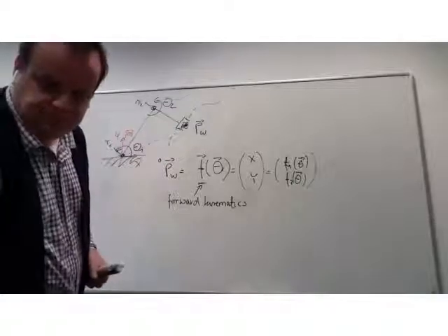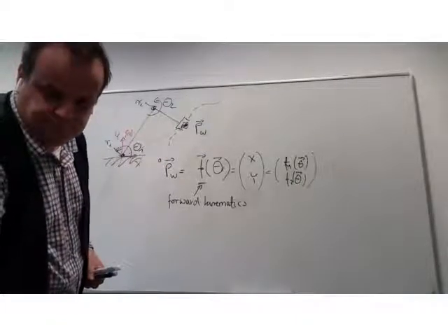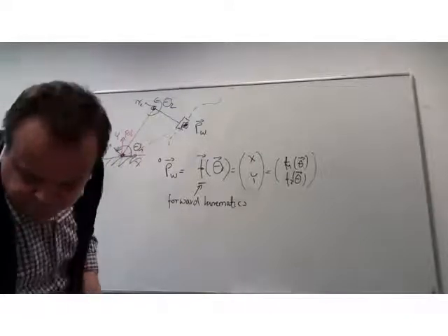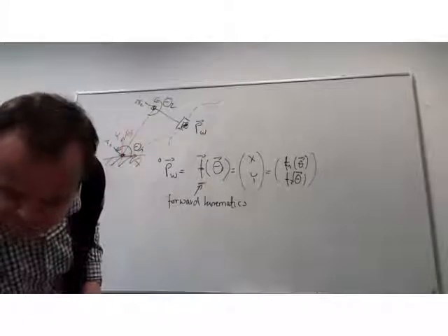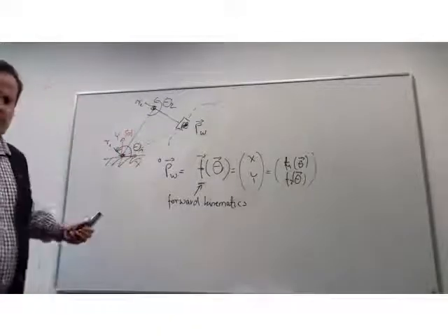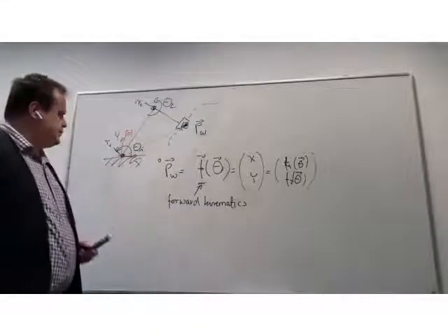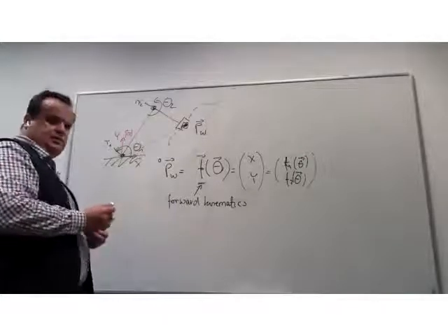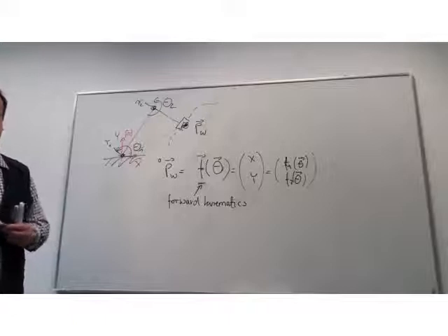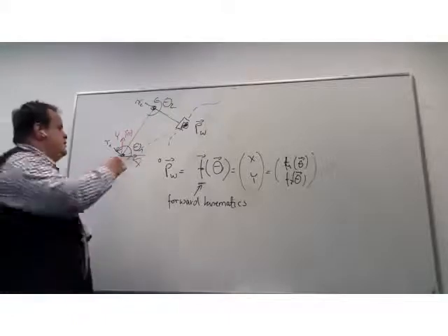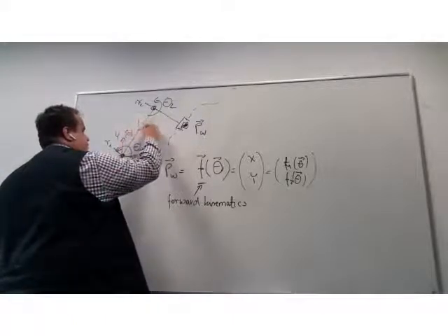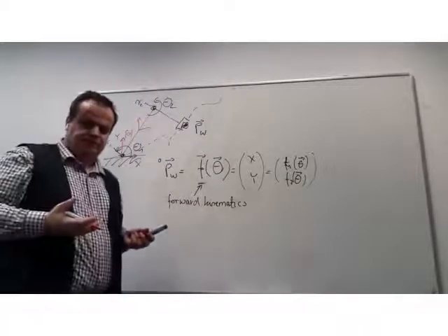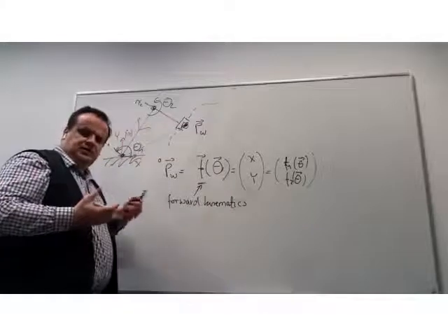So to do that, in such a robot frame, we need to identify first what are the moving parts of the robot. So we will need to assign additional coordinate frames to our system, which are attached to independently moving parts.